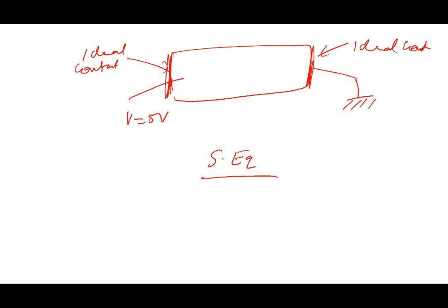What do you have to do? These are a set of mathematical equations, differential equations, boundary conditions are given to you, you solve it, what will you get? You'll get your IV characteristics. So one way of analyzing a semiconductor device is, all the equations are given to you, boundary conditions are given to you, it becomes a mathematical problem.